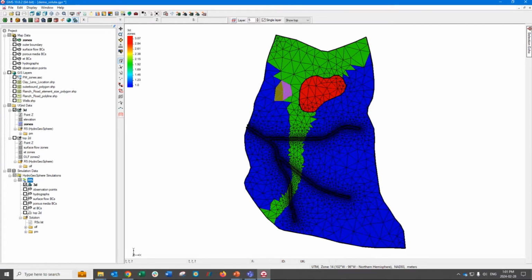No solute transport, no density dependent flow, lots of other things as well. The list of HGS features and functionality is so long that we could be here for quite a while, but basically we've tried to design the GMS interface around the core functionality of HydroGeoSphere, which again is coupled groundwater surface water flow with evapotranspiration. But using the blended method of making modifications to the grok file after using the interface to develop the initial grok file, you can incorporate some of those more advanced features.